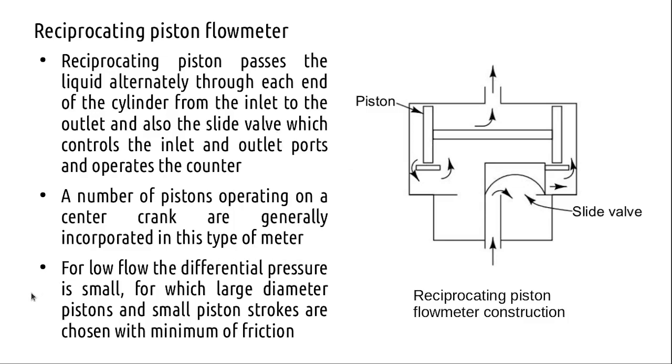The key idea in positive displacement meters is that you have a chamber of precise dimension, and you know what quantity of fluid gets into this chamber. The simplest example: you want to measure the flow rate through a pipe. Say I have 3 empty glasses.